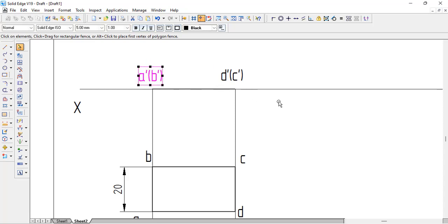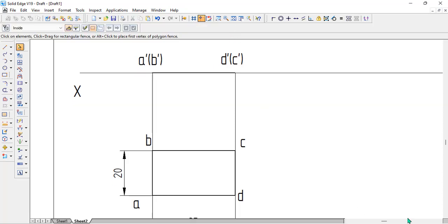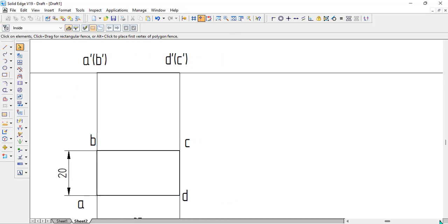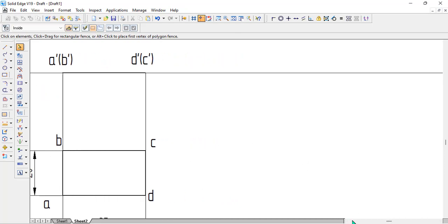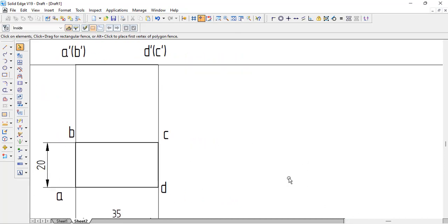That's fine. Okay. So now the important thing is how exactly in the second position. In the second position, they asked us to find the inclination. So always we need to remember here the resting edge is AB. So this is AB. It will be on the XY line. And normally whenever we take up this line, this end is on the XY line and this end will be moved up for any inclination in order to get the top view.